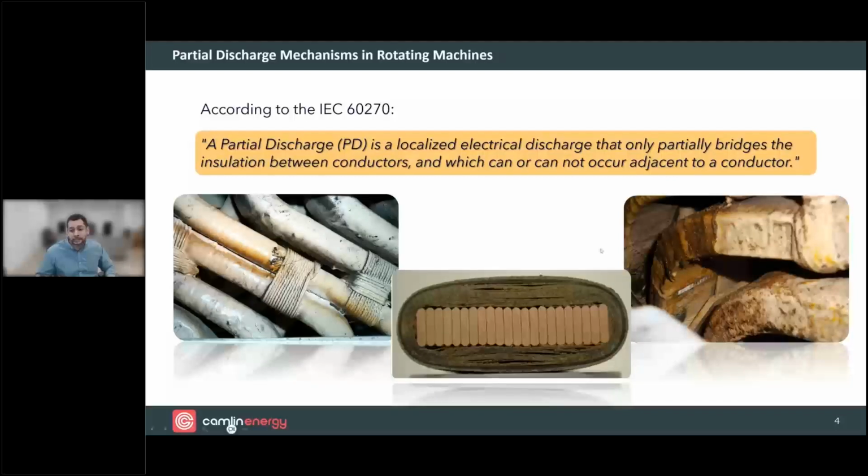at that site. Similar to here, here's an indication again by the white chalky substance seen visibly here, that there's discharges due to defects in the winding between the overlap of the end winding insulation into the slot section of the coil before it enters the core.